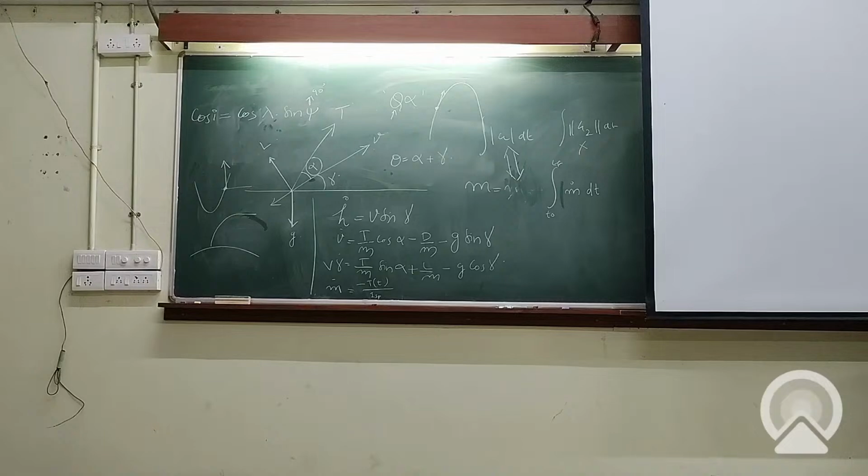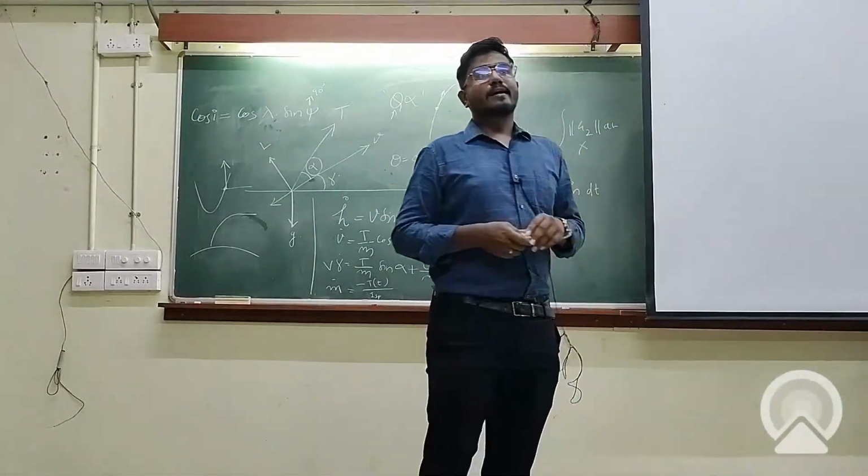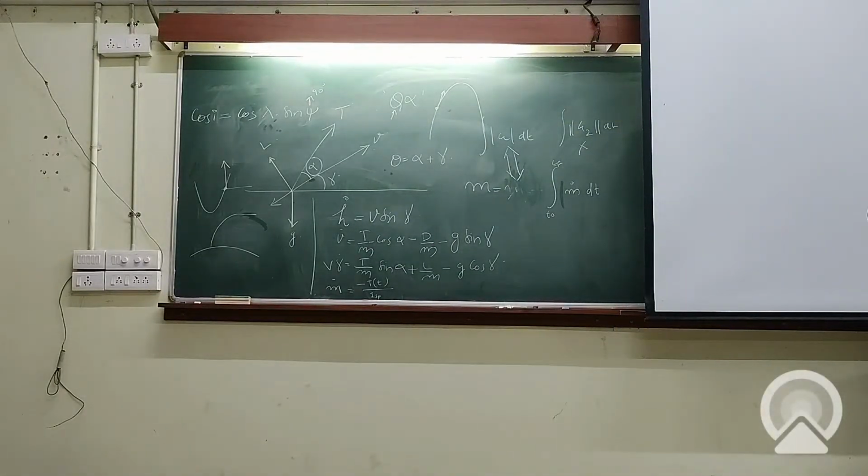Then again, you cannot fly any arbitrary bank angle, because the bank angle will have an effect on this g, since effectively you are reducing the lift and contributing towards side force. So it will have an effect on the acceleration. Your drag will be more, and the acceleration levels the capsule is experiencing will also be very high. So these are the two constraints I want to talk about when it comes to re-entry vehicles. Okay, that will be all about the mission design for today. In case you have any doubts, I'll be happy to answer if I can.